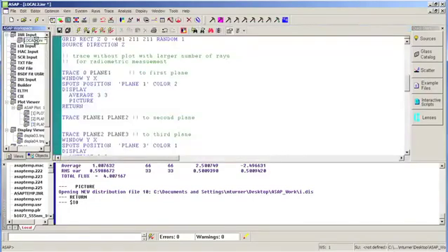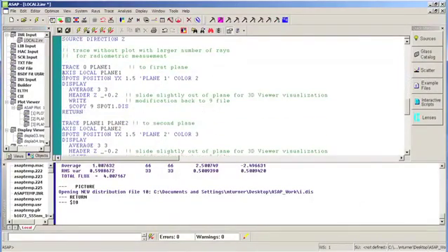And that's actually quite easy to do with ASAP. It just requires a different command. And the particular command we're going to use is what's called the axis command. The axis command, in particular with the local modifier, allows you to change the orientation axis for your next calculation, in this case, the spot's position command. What our axis local, in this case plane 1, is saying, for the spot's position command, define a window that is defined based on the local coordinate axis of the defined piece of geometry, plane 1. So now we're going to define our analysis window in the coordinate system of plane 1.